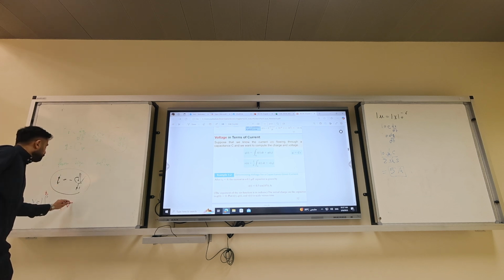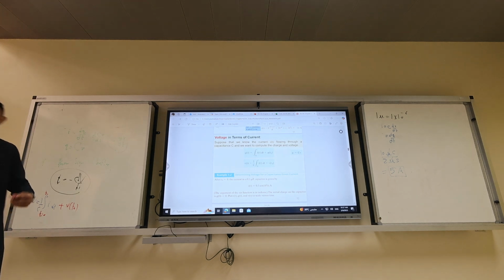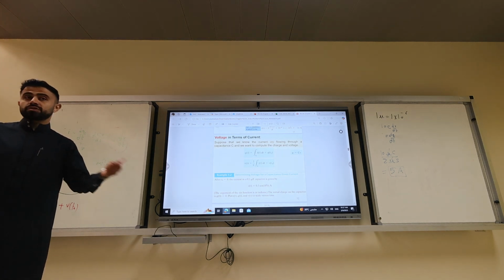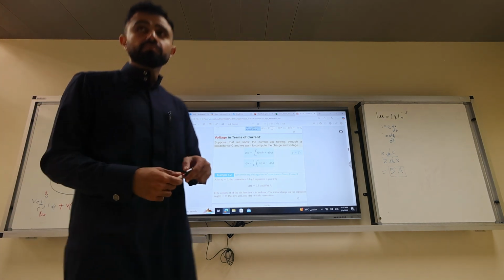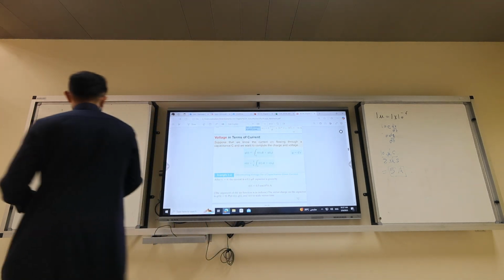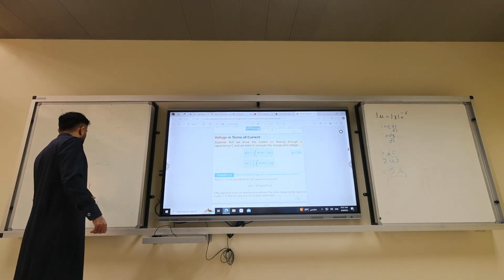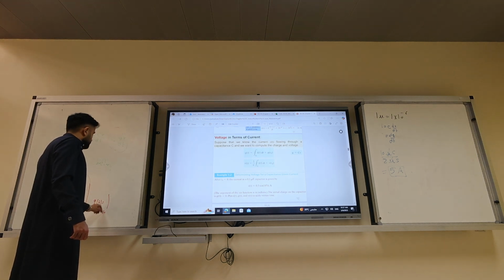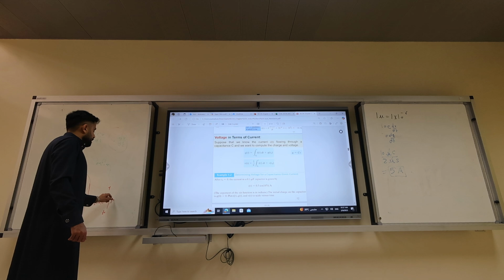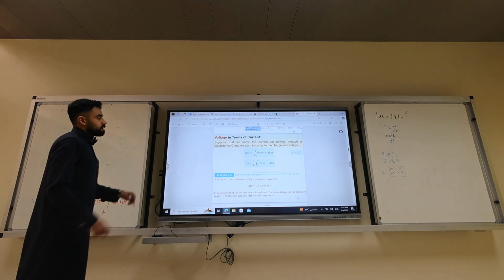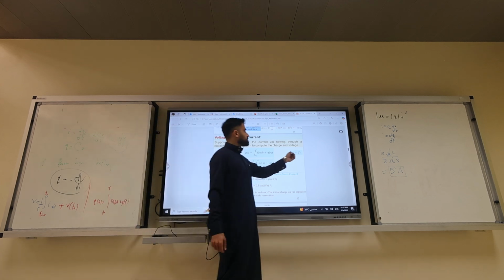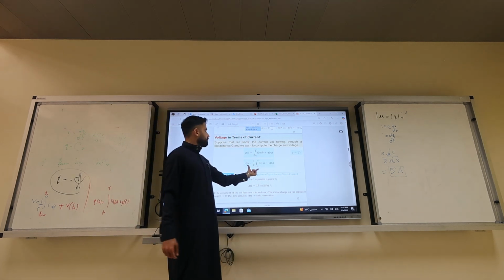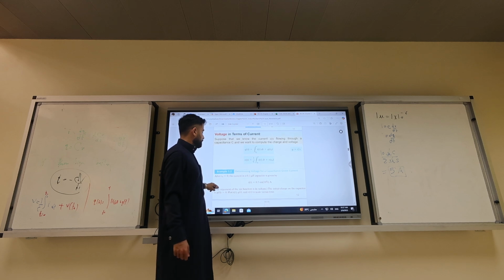The initial voltage. Sometimes the capacitor has initial voltage if it was storing some element. Same for the current. What's the equation of the charge? It is nothing but the integral from t naught to t of i(t) dt plus Q(0). Note that the equation Q equals CV is still valid, and that's how we found the voltage equation.